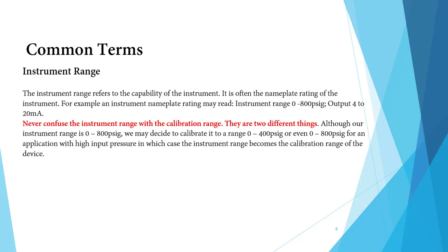We can have a 0 to 800 psi instrument range, but we can calibrate 0 to 400 psi or 200 to 600 psi, depending on your application.